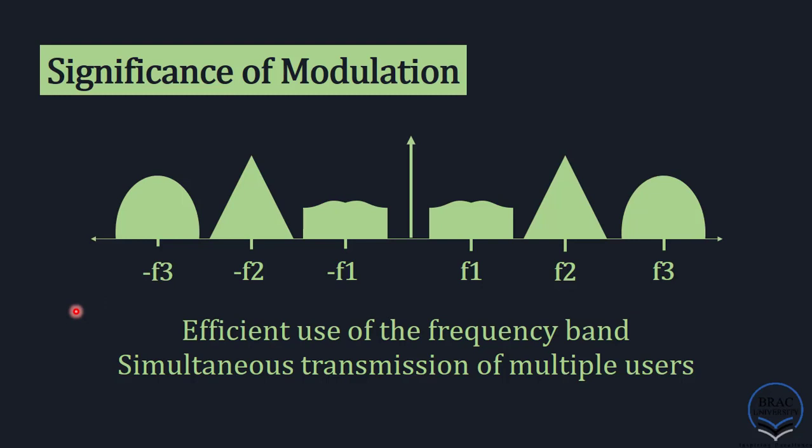We have megahertz level frequency available to us. So why should we be limited to the 4 kHz range? We have a large spectrum of frequency available. We should use it properly for increasing the capacity and the quality of communication. The main theme of modulation is to convert the low frequency signals and shift them to higher frequencies. That is what we have done in the modulation process.